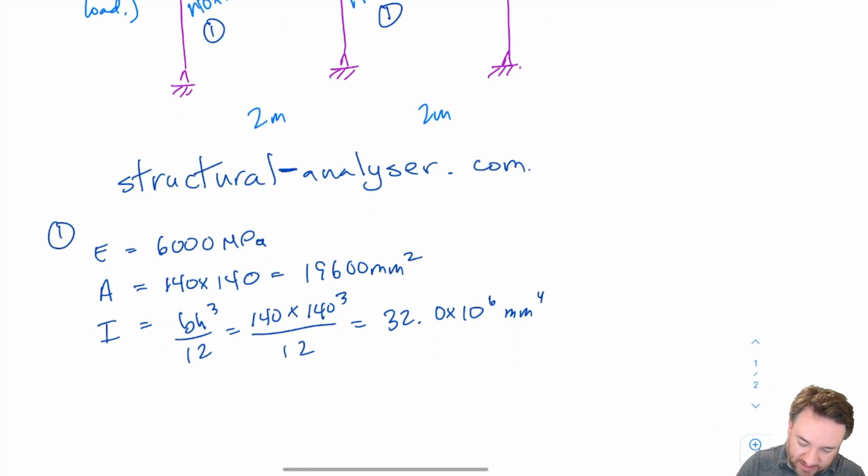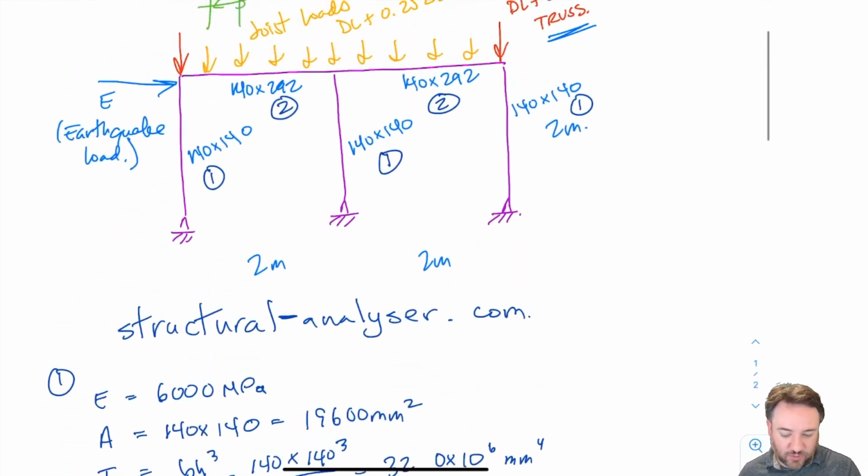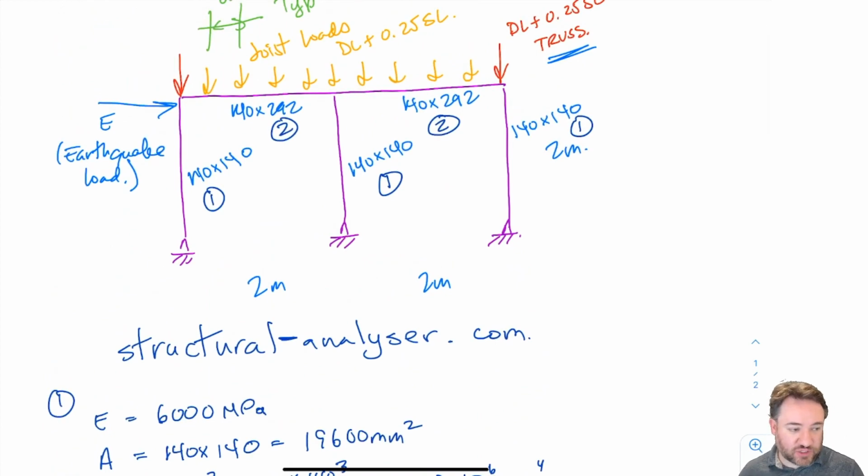For 2, obviously I am doing this in whichever is the bending axis direction, the way that they're going to bend. So the columns are square, so it doesn't matter. The beams, I'm assuming, are sitting in the strong axis direction for strong axis bending.